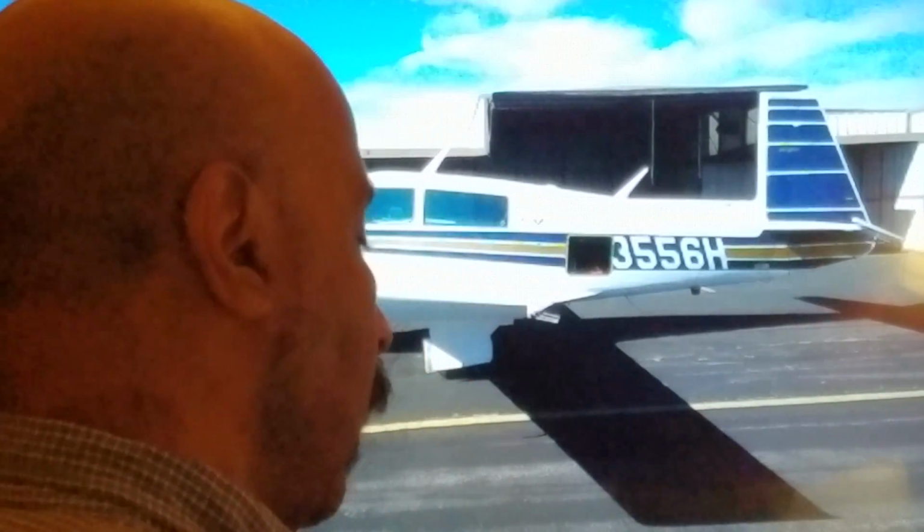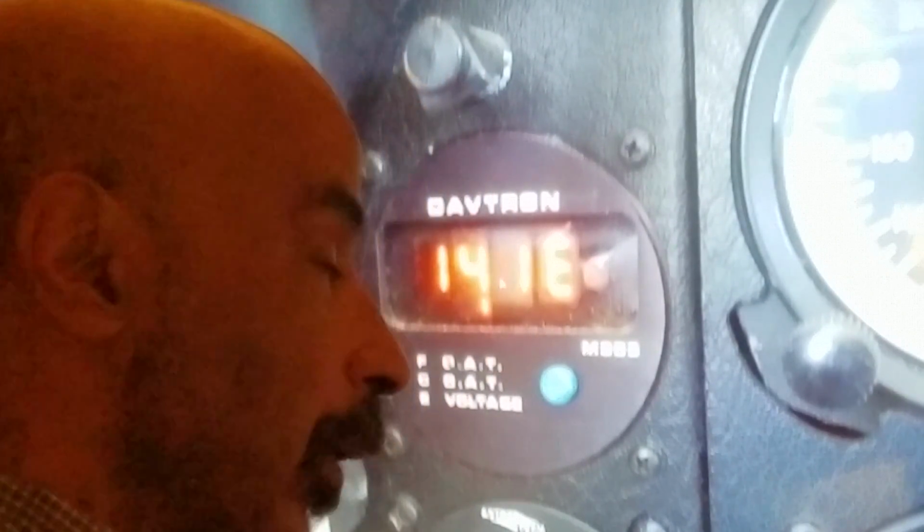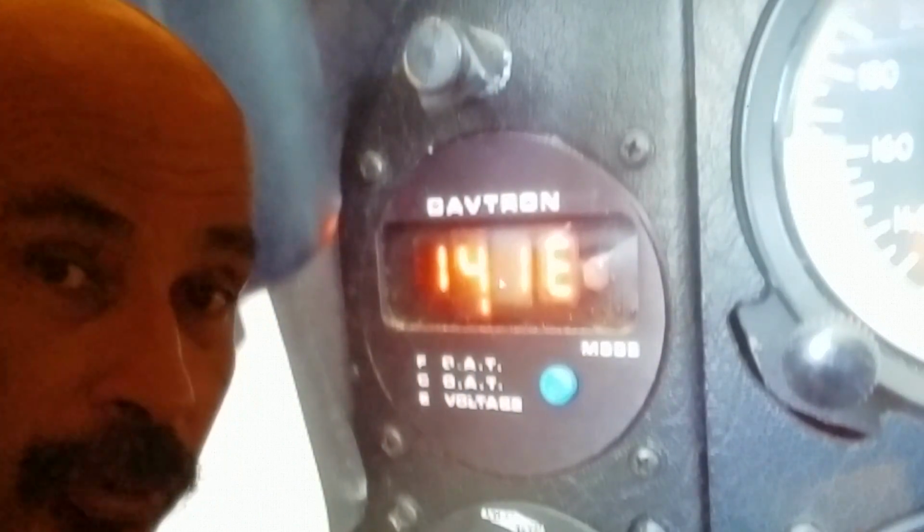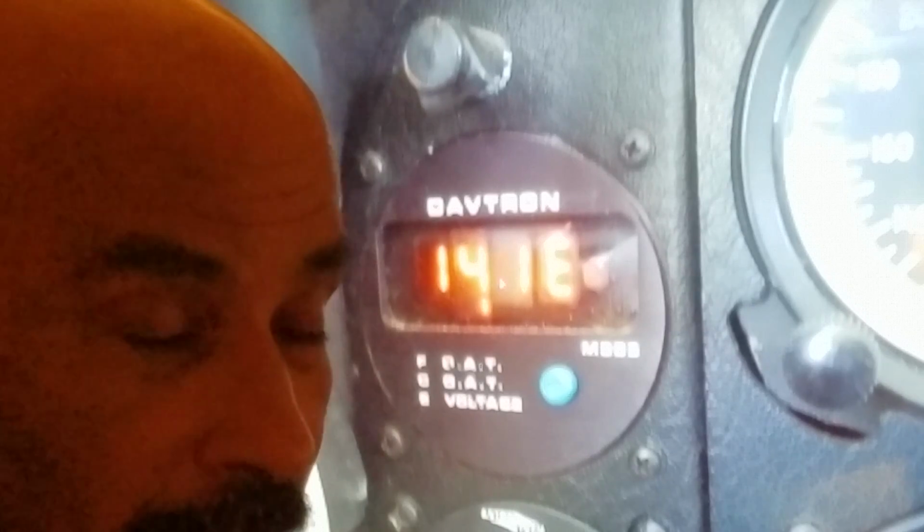We left off in the last video and we began to talk about the purpose of this outside air temperature gauge. The outside air temperature we talked about could get the airplane into trouble if you were to fly into visible moisture like clouds and the outside air temperature was cold enough to freeze. We said that if you knew that the air was cold enough to freeze, you wouldn't want to fly into visible moisture if you did not have an aircraft that was certified to fly into known icing.